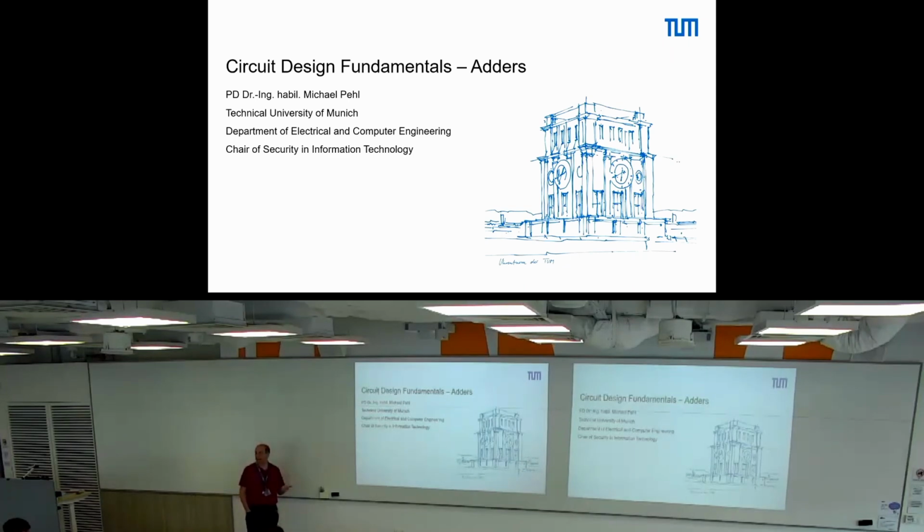If we compare this ripple carry adder as a baseline with some serial adder, what are benefits and drawbacks when going from ripple carry to serial addition? Benefits and drawbacks of serial adder compared to RCA, ripple carry adder. Lower area, shorter critical path, so higher frequency. Any drawbacks? It requires more clock cycles, so it has a higher latency.